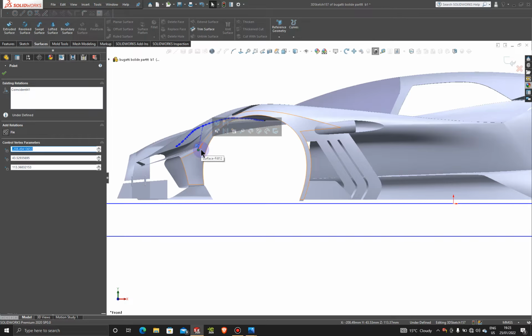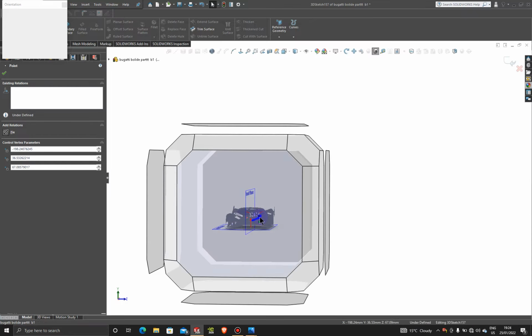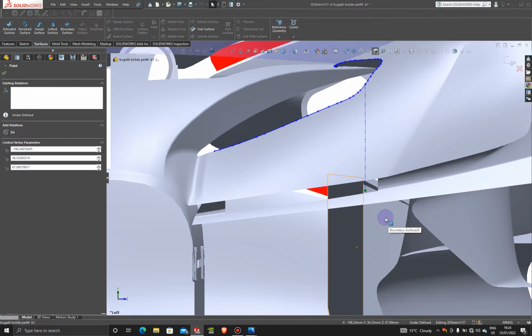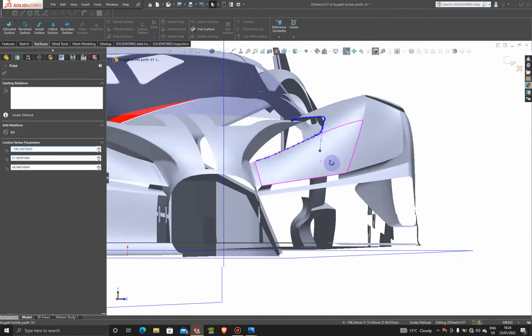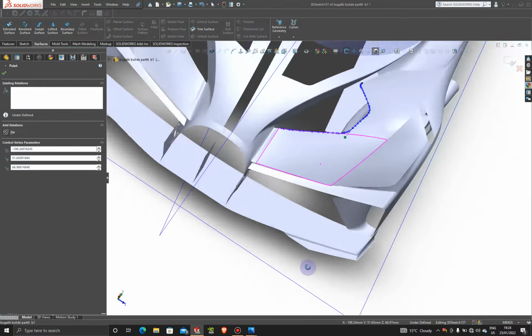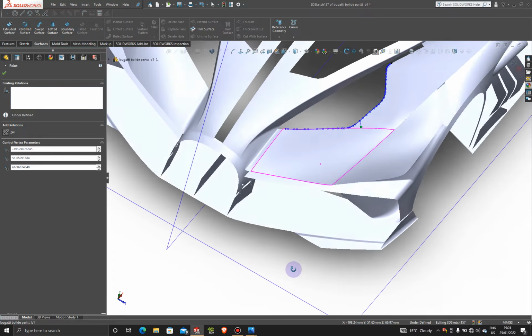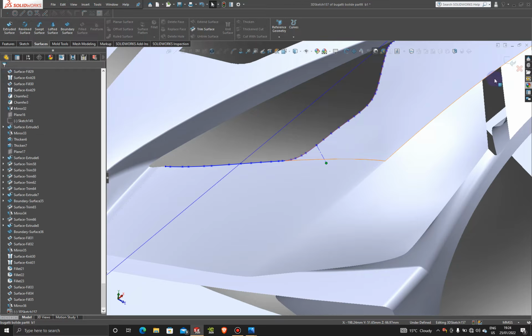It snapped to that surface, so let's Control Z. So about there. And let's fix that point from this side as well, this angle. Let's go up to about here. Okay. All right, so that direction of pull looks good to me. However, we can adjust that by manipulating this line afterwards. All right, so press OK, exit the sketch.